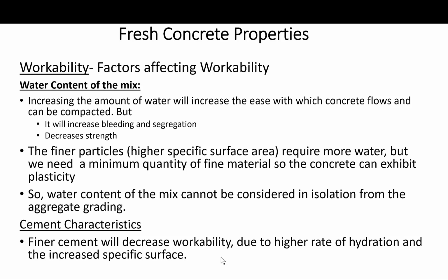But apart from reducing the strength, increased water may also lead to segregation, which is the settling of the coarse aggregate, and also bleeding. So in general, any collection of particles requires a certain amount of water to achieve a plasticity, so it can be worked.